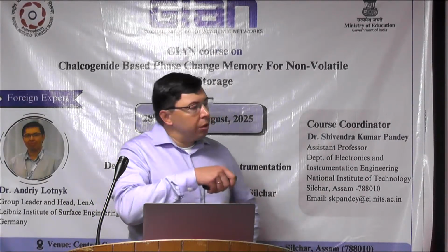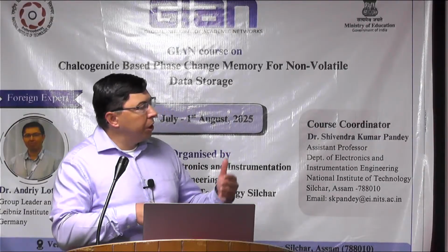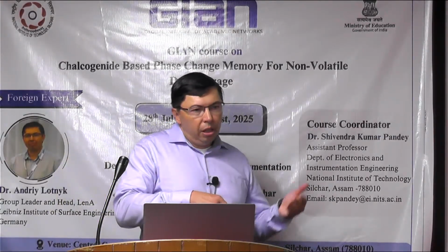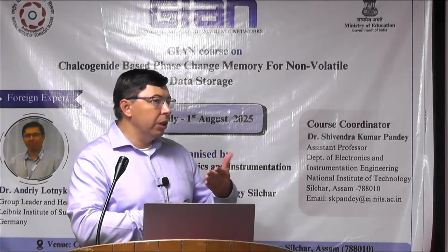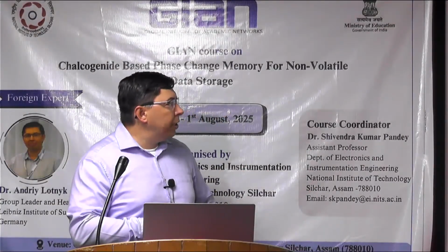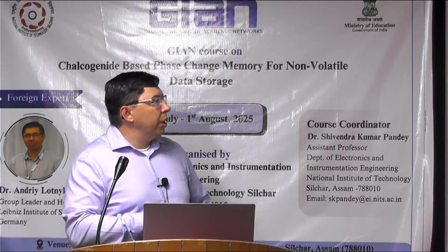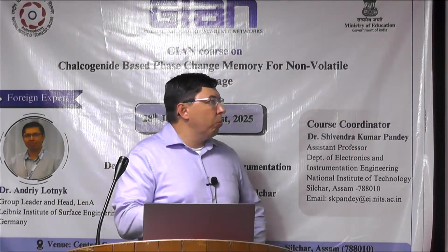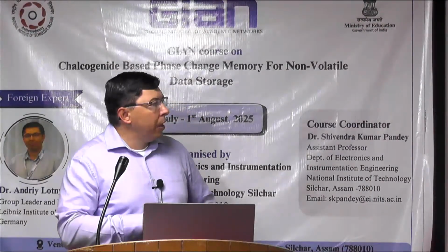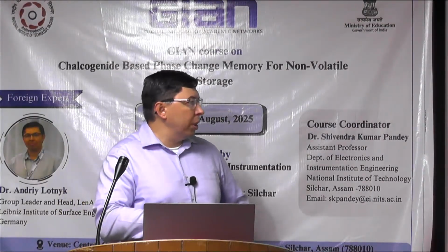Why is this? Because the crystallization of amorphous materials starts from this native oxide layer, so you have an additional interface, and you influence your crystallization kinetics, and in this case also data retention in the amorphous state is reduced by the presence of the oxide layer, since this oxide promotes crystallization.